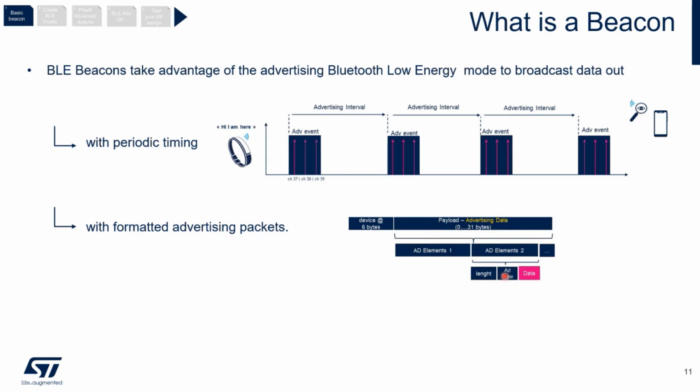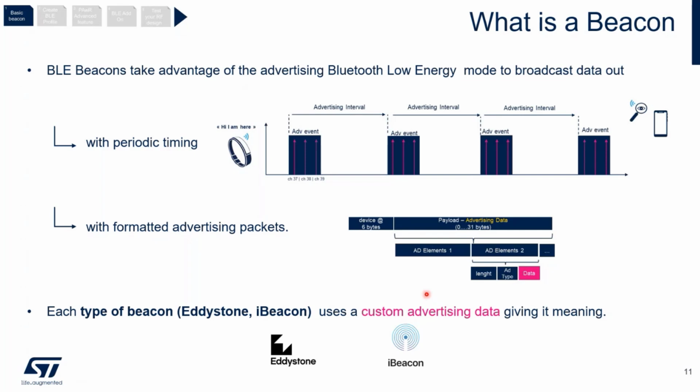So again, a BLE beacon reuses the basic concept of advertising. I'm pushing some data over the air at a specific interval, and I can push whatever data I want. I just need to prefix the data with an advertising type. Now, what is the magic behind it?